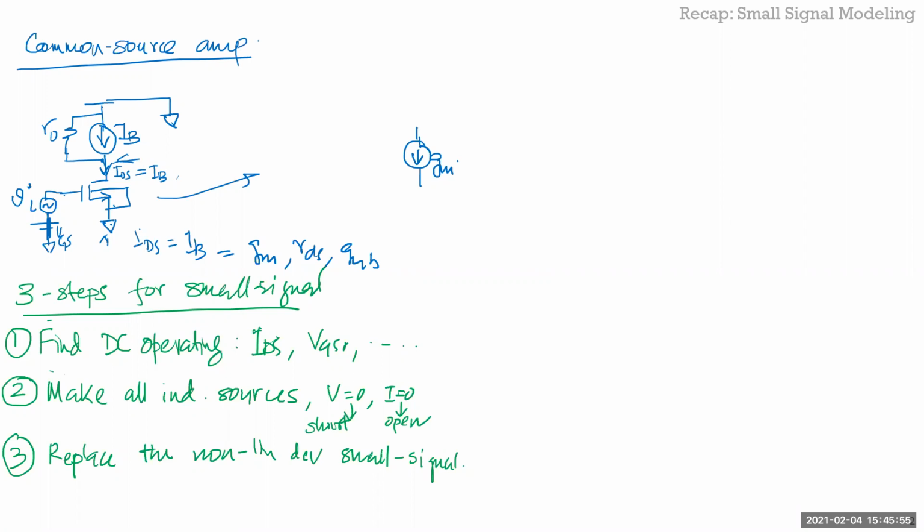So you have the transconductance, which is GM VI, right? So that's drain to source. So let's draw this as the source terminal. And the bulk and source are shorted here. So this is both your bulk and source, which is ground, right? Okay. And the input is given with respect to this node, VI. This is your gate terminal, which is just hanging because its input impedance is infinite, because this is the low frequency model where the caps are not there.